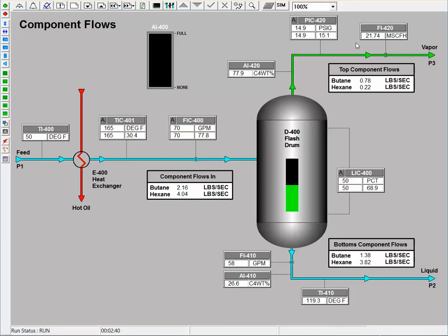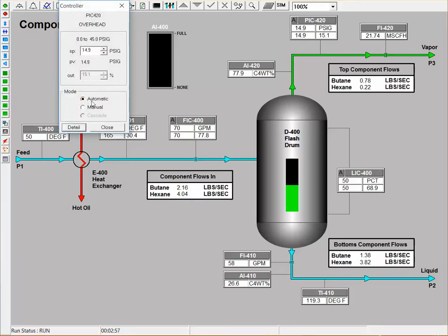This breakdown also clears up some trickier points regarding separation. For example, a change in pressure has the potential to worsen purity in both the overhead and bottom streams. So now I will provide an example as I change the pressure of the system, and we will see how the overall component splits change for the system.